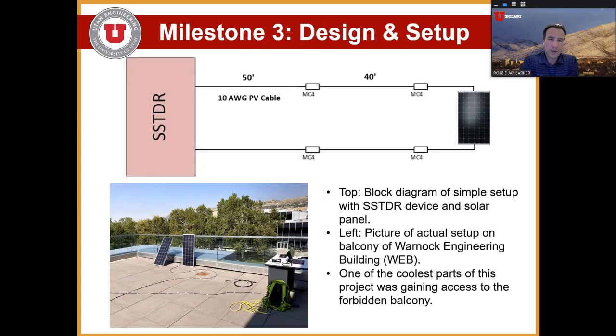And then it's a bit of a pivot, but all of this was, like Sam said, solar panels interact with the SSTDR signal much like a capacitor. Electrically, they look like capacitors to electromagnetic signal on the line. And so what we wanted to do next is see how the impedance of a solar panel changes with varying environmental factors, including irradiance, just intensity of illumination, and other weather factors such as moisture and temperature.